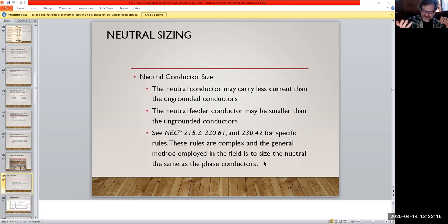Well, they pull three wires into your house. So two of them are hot, and then one is the neutral. And the neutral basically lets the current travel, because you have to have a return path, right? So you get the current coming in, you got to have current going back out. And the neutral rides the current back out to the transformer. And so you'll run it through the house. In residential, it's white. In commercial, more often than not, it should also be white, the black, red, and white. When you get into industrial settings, that changes, but we're not going to cover that really.